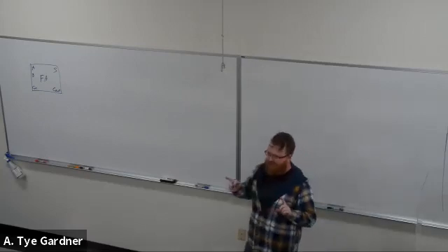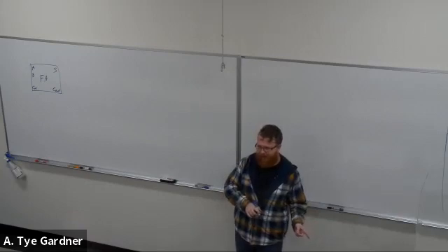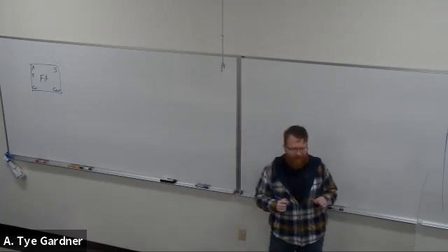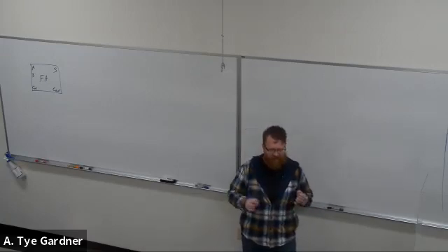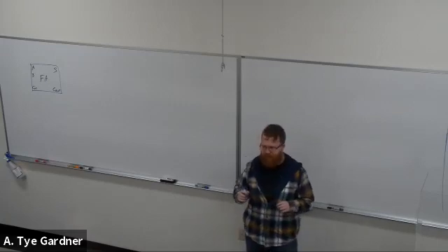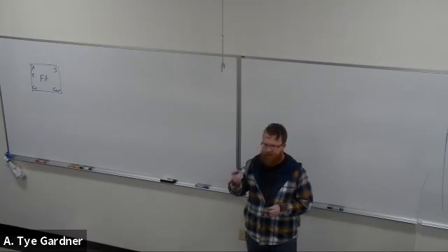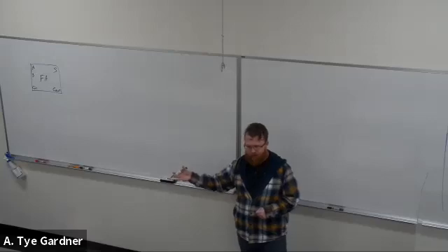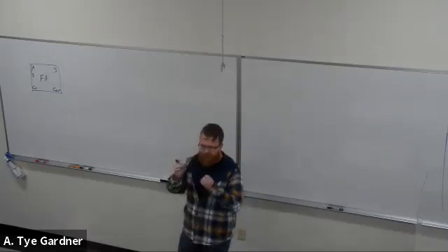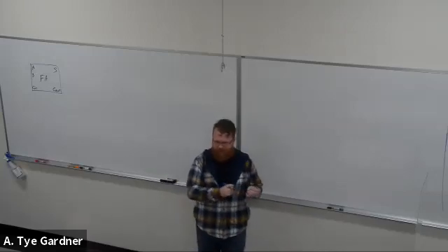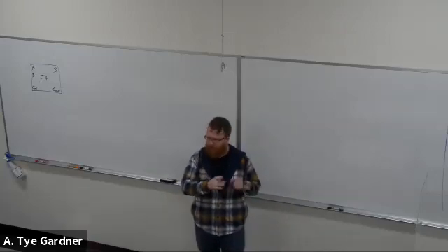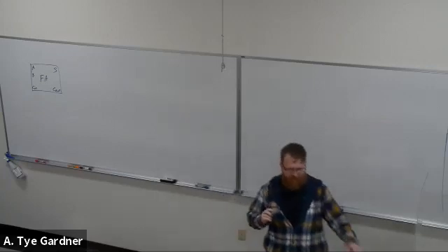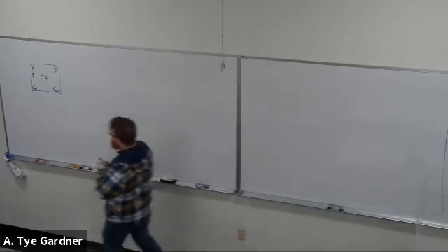Initially you were going to have to build a 4-bit full adder on a breadboard, but that really is just a test of your dexterity and organization skills, right? And it takes a very long time to do that, especially when you're new. I don't see it serving as instructional as taking the opportunity to use what we learned with building the initial full adder and turn it into VHDL, so that we have a concrete connection between something that you did on the board in the physical world and code. But because we're doing the full adder as a lab, I don't want to give you all the answers to that. So I'm going to create a new component.